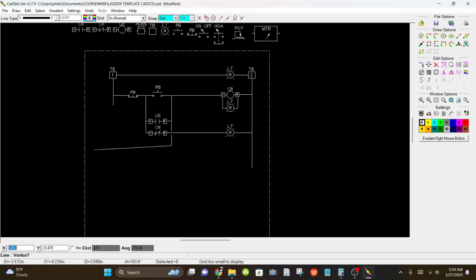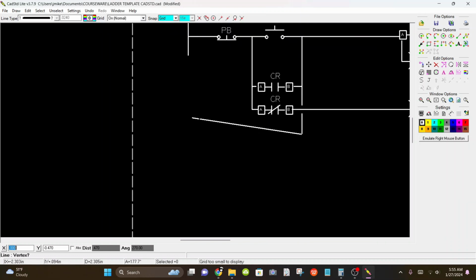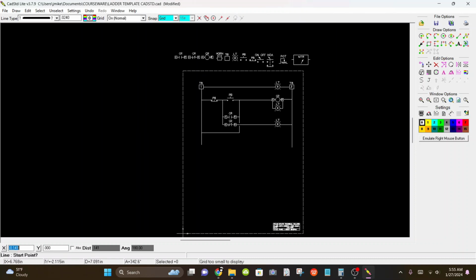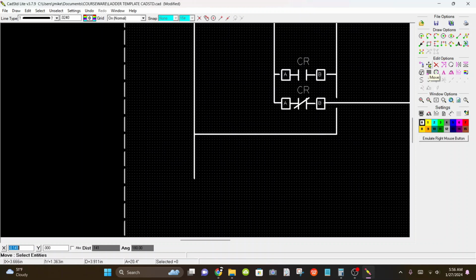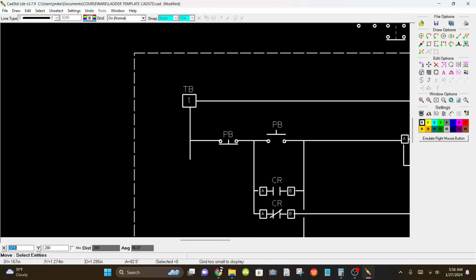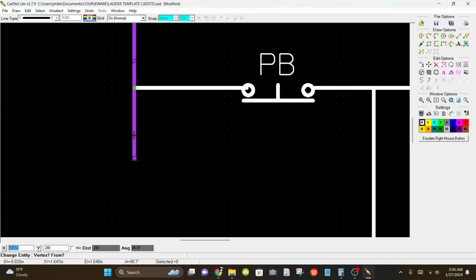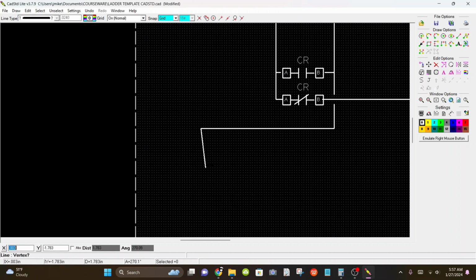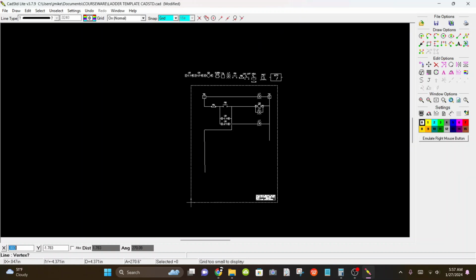So when the relay is off, it'll turn on that yellow light. Now we're going to use the right side of that normally open relay contact for the power for our PLC inputs and outputs. So we're going to come off of that terminal on the normally open CR. We're going to jump over that wire that's going to the yellow light, and we're going to make the rest of our power rail. Because we can't use this power rail for the PLC inputs and outputs. The PLC inputs and outputs can only be hot when the relay's pulled in, and this is what's going to make that happen.